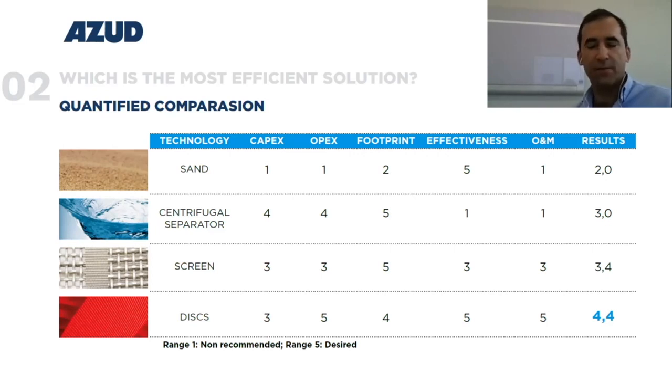This is, for example, the disc filter. During backflush, the discs will separate and will allow to release the trapped particles much easier than a screen, or in case of the media filter, also the media can expand during backflush, although it's much more difficult to find the equilibrium during the backflush and then to assure that the media will settle down to the same position. Also, you have the risk that part of the media will go out to the drain.